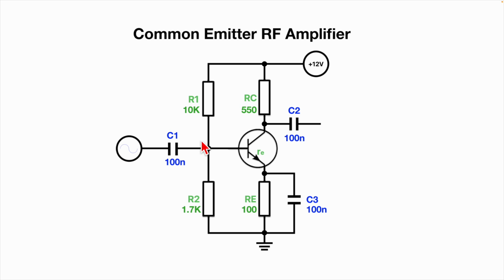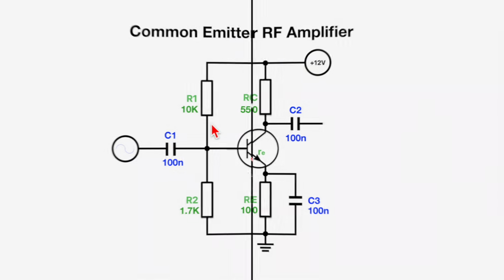So this basically makes sure that any variations because of the DC beta, which cause the current to rise and fall more or less, will pale into insignificance compared to the current that we've got flowing through here, so it won't upset the DC biasing. Now, it doesn't bulletproof you from anything else to do with beta, but more of that in a moment.